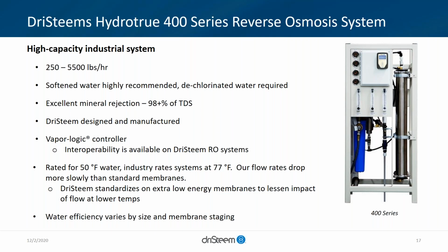Dechlorinated water is required. The thing is, the RO membrane will get about 1,000 ppm hours. So if you have 1 ppm, it can run for 1,000 hours before it's deemed unacceptable from a rejection perspective. But as you're going through time, it's not like it goes from perfect to terrible at that 1,000 hours. It's a gradual decrease of quality over time.